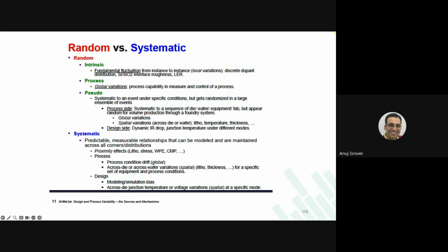Similarly, you will also find another parameter called A. I'm talking specifically about the ST extraction deck. In any other technology, you will find a different variable name, like X or P or Q or R. Someone can use a variable X, another can use Y, and someone can use a variable name Anuj. That doesn't make any difference. What you're talking about is the intent. In ST technologies, you will notice that there is a variable with letter A, A equal to something. That talks about the stress effect in terms of the extension of the active region beyond the gate poly.